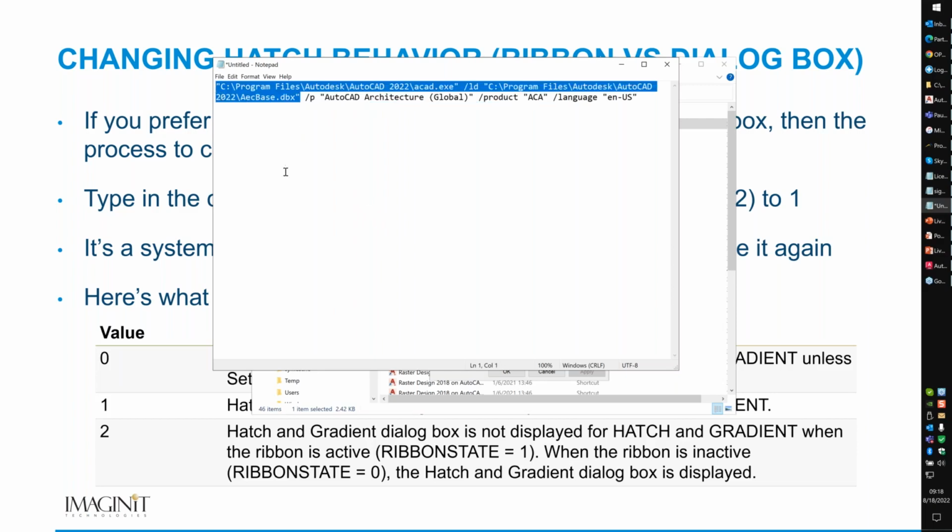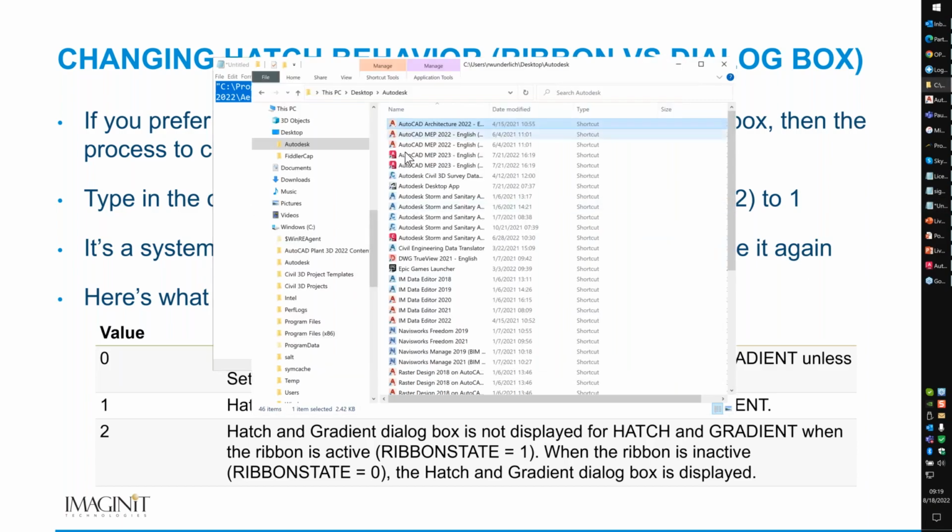Usually with Civil 3D, if that's the only thing installed, it usually works fine. If you have multiple products installed, it's important to know that you'll always want to double click the DWG, and you always want to have DWGs associated to the AutoCAD DWG launcher, and it should be grabbing it. If it's not, you may have another issue. Also, if you've installed additional products after you've done that, sometimes you need to go back and reset it. So those are those things.